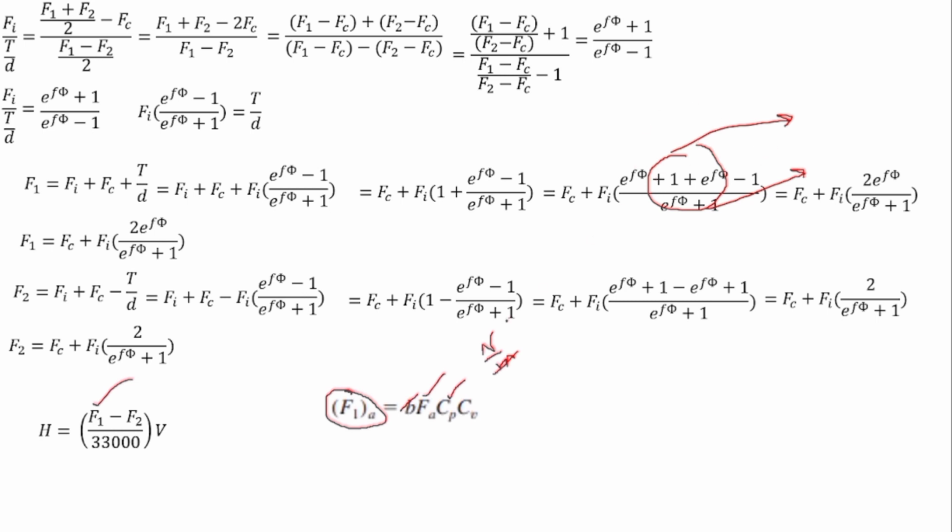The belt will slip over the pulley, so you will have to put a pulley correction factor as well. And similarly, since this belt is designed for a particular speed, you have to put a velocity correction factor as well if you get another velocity for which it is not designed. So these formulas will be used in the analysis and in the design.